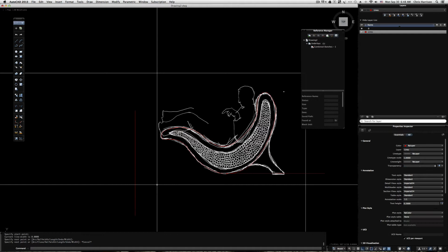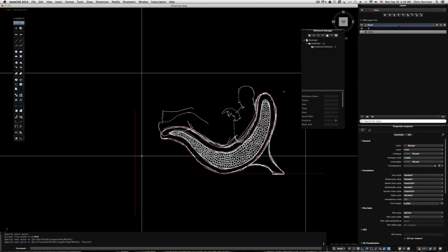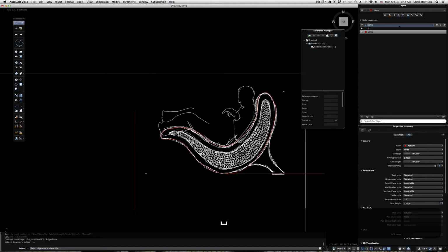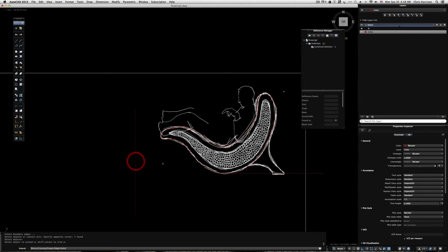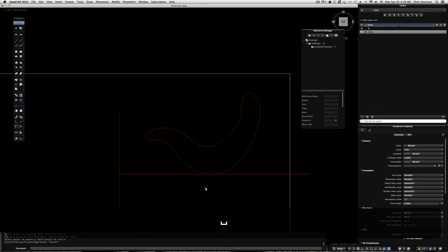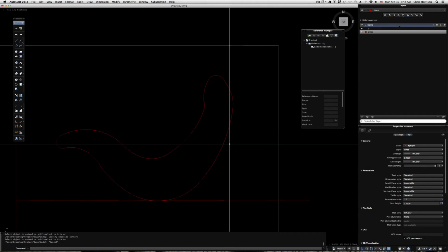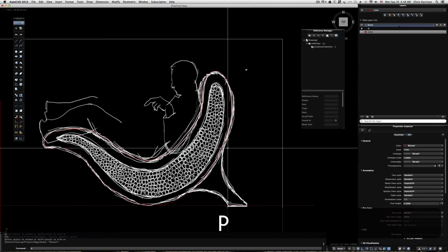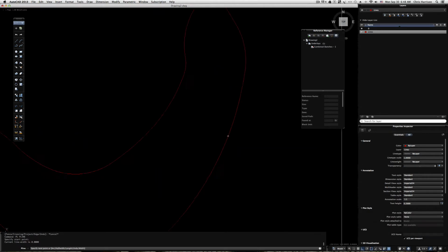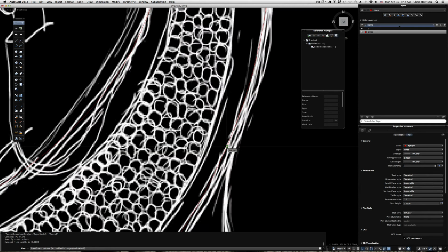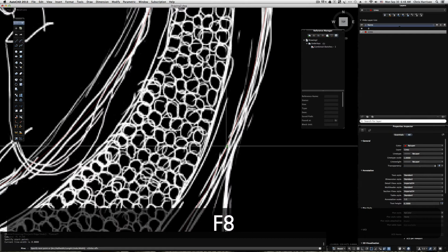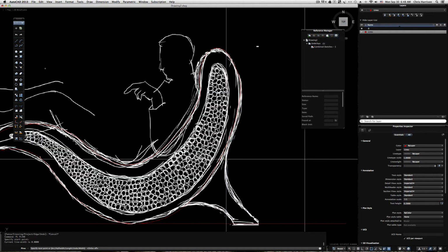Another common tool that you use is called extend. So I'm just drawing a line. I'm going to hit EX for extend, enter, select the line, enter again, and then select the line that I want to extend to that point. And that's going to begin to create my base. Now I'm going to come in here again, and my O snap is still on. And so is my ortho, so I'm going to turn ortho off. And let me go ahead and turn that O snap off too.